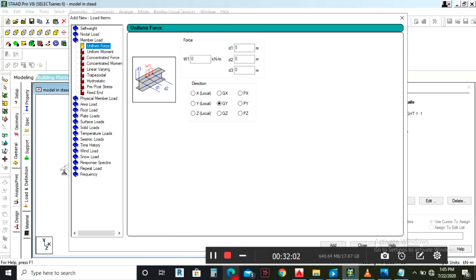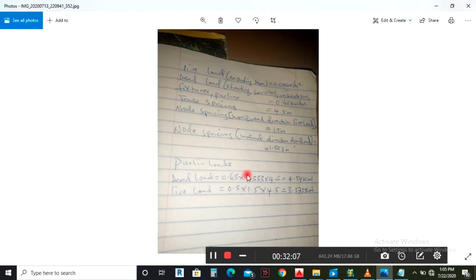So now from our old load analysis, the first design we were not putting purlins, we were not doing truss spacing, so we multiplied our load by the distance so that it fixes on those nodes. But in this design we have modeled our purlins, so we are now doing truss spacing. So we are not including this distance.